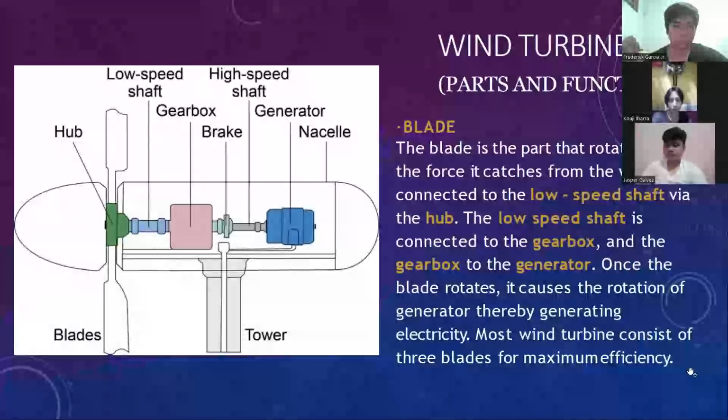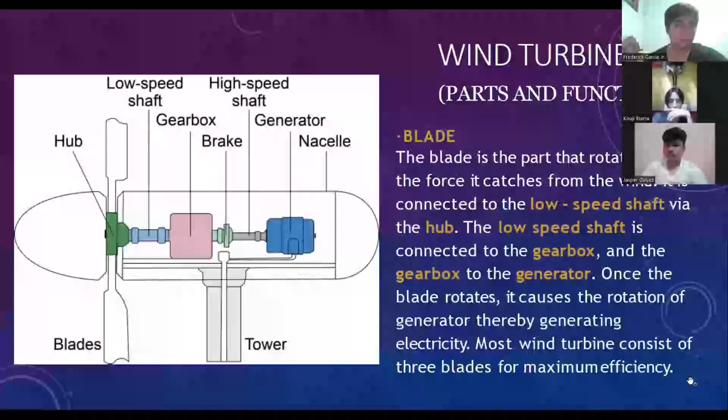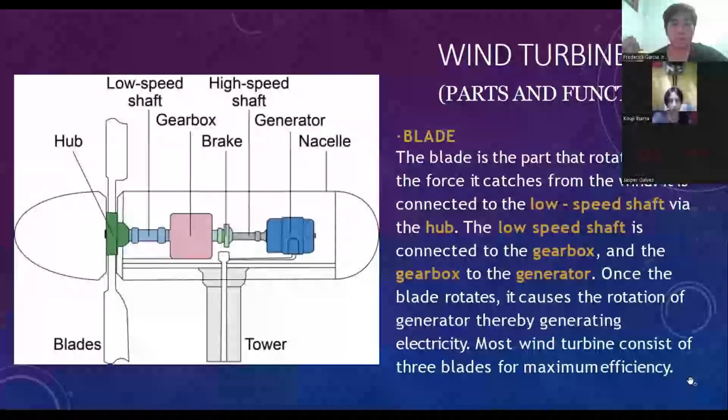Okay, thank you. Now, a wind turbine turns wind energy into electricity, right? Using the aerodynamic force from the rotor blades, which work like an airplane wing or helicopter rotor blade. When wind flows across the blade, the air pressure on one side of the blade decreases. The difference in air pressure across the two sides of the blade creates both lift and drag. The force of the lift is stronger than the drag, and this causes the rotor to spin.